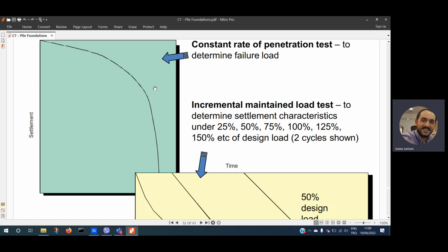That's what we call yielding: yielding of the material, yielding of the pile itself, shearing of the soil. All the same thing, it goes plastic. This is plastic, non-reversible behavior. And we can simply set our limit from this graph as a result of the pile test.